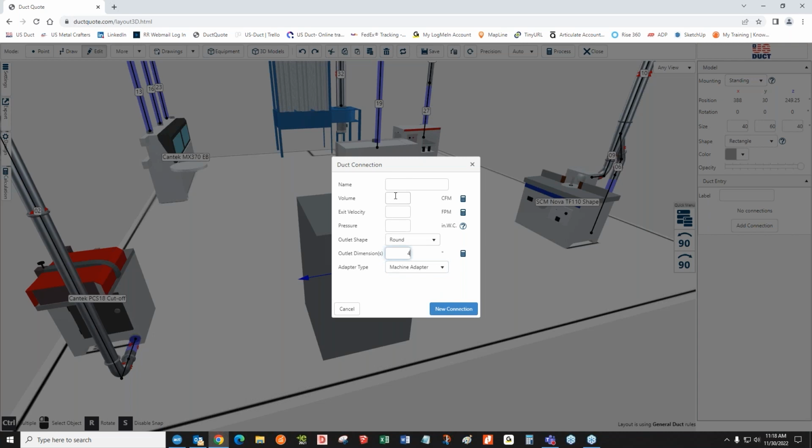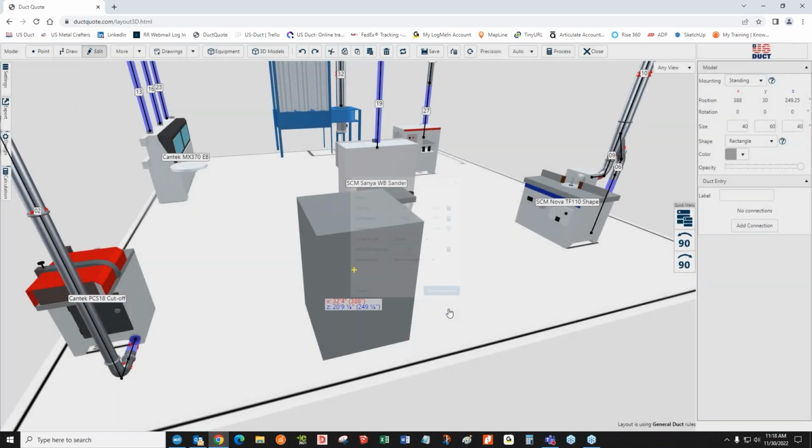4-inch. Now we have to actually give it what it is that we're going to be creating as far as the pneumatics here. So this is a wood system. We're going to run it 4,500 feet per minute. And I can use the little calculator over here to figure out how much volume that'll pull. And we can say, okay, and now I can actually select.